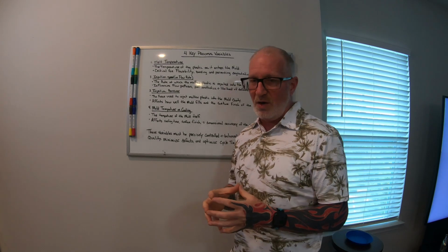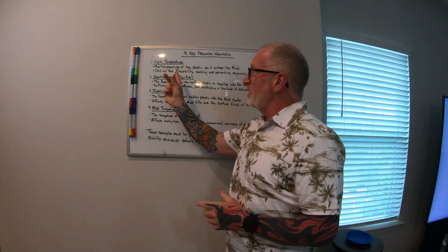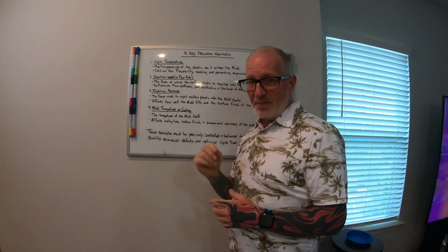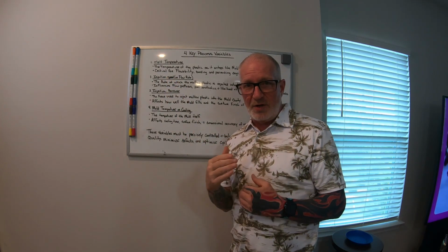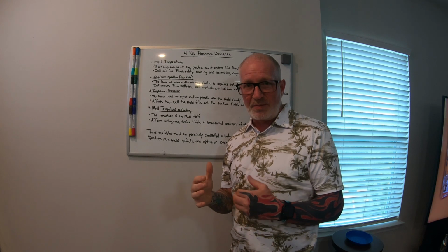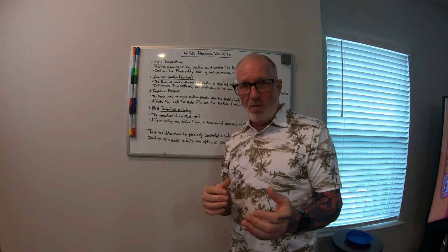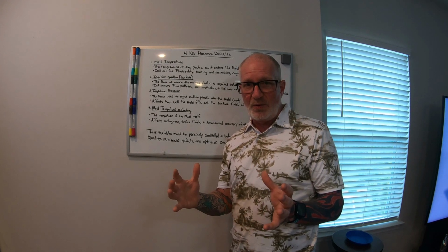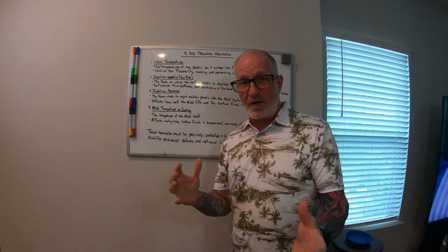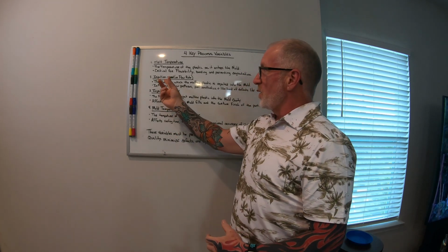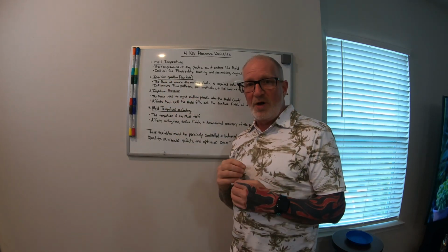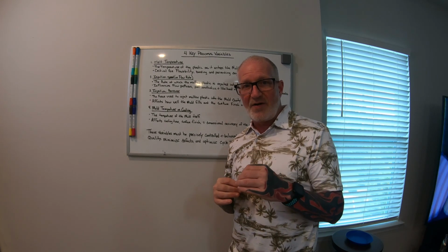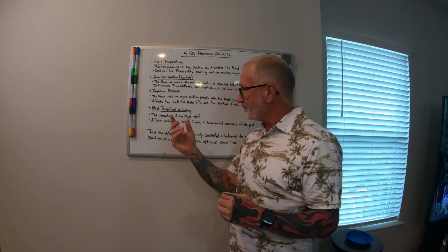So me personally, what I always do is I do the first one, get my melt temperature where I want it to be at. Then I'll inject a part. Most companies, whenever you're doing a PPAP sample or something like that, you'll know what the shot size is supposed to be on your part that you're actually getting ready to mold. Some people don't, so you're kind of like guessing. So you'll start off with a fill rate of what you think it might be to fill that part out, and you want to fill that part to about 95 to 98%.